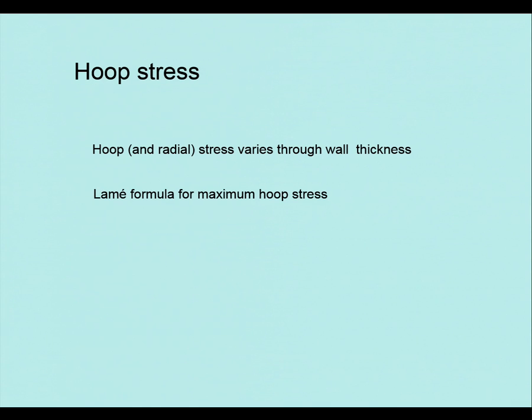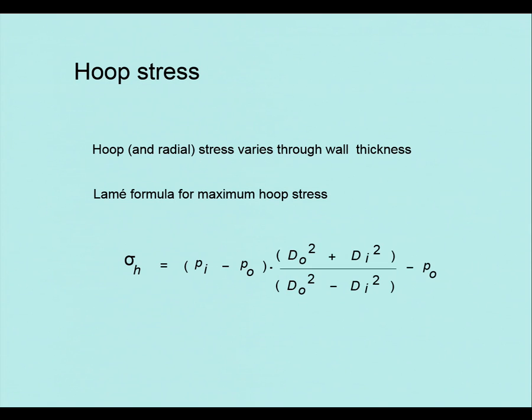With thick wall, it varies throughout the section. It's greater on the inside than it is on the outside. So to do that, Lamé produced a theory which I can show you graphically, but you don't really need to worry about it. But that's the formula for it.